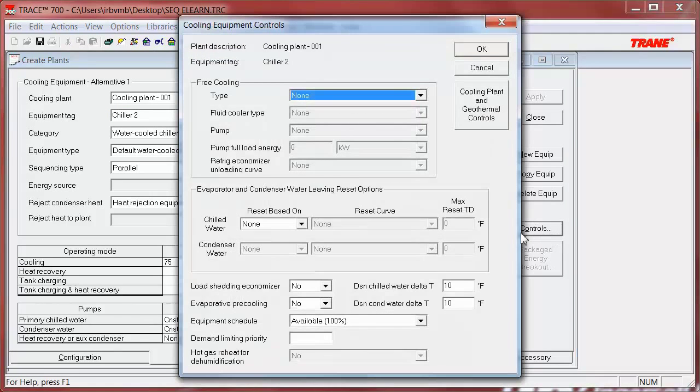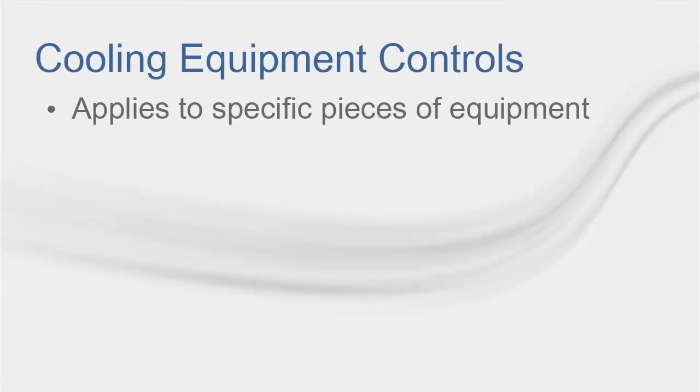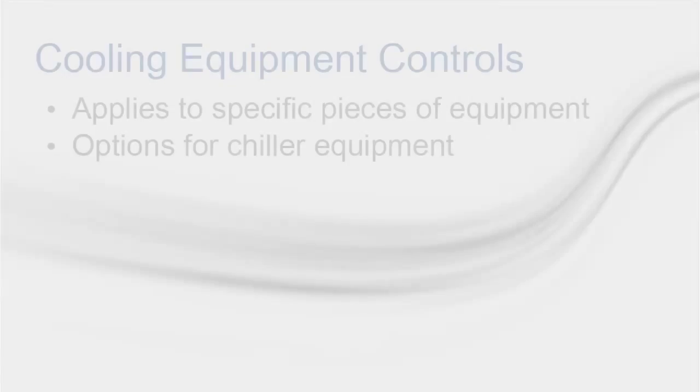Once you have clicked this button, you will see a new window appear with a number of different configuration options, which we will now review. Cooling equipment controls relate to specific pieces of equipment, so when trying to apply these strategies to multiple chillers, you will need to set up these controls for each chiller, or alternatively, you could set up the first chiller completely and then copy that chiller.